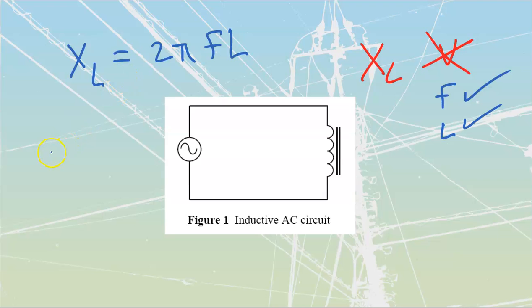And then the last part that we have over here is 2π. 2π is not something that we generally use a lot inside of electrical. We'll see it in a bunch of formulas, but we don't do the deeper analysis of it. What 2π is, it is dealing with the radians of a circle, or in other words, how far around. It's a rotational type of thing that's going to be happening. We, generally speaking, are going to deal with dividing our circles down into degrees, not into radians, but radians is just another form of splitting apart a circle. And when we're dealing with radians, each half of a circle is going to be defined by a single π. So a single π for that one, as well as a single π for that one, which means that if I've got 2π, that defines an entire circle. So anytime that you see this 2π, that just means that we're looking at something over the entire 360 degrees, or over the entire sine wave that we are going to have. It indicates that there's something sinusoidal or circular about it.